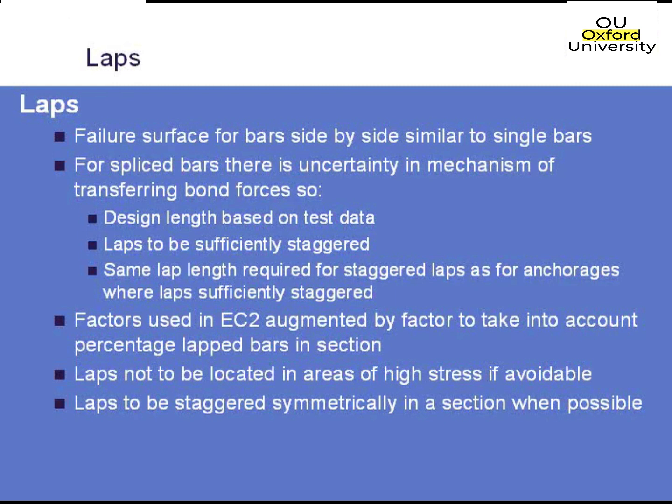Generally speaking, some guidance that you should be using is to make sure that you don't locate laps within areas of high stress if you can avoid it. You should also make sure that you stagger laps. Sometimes it isn't possible to stagger laps very well, particularly if you're coming in from a pile into a footing connection or something like that. In those situations, it is quite difficult to get your laps staggered. But generally speaking, if it's possible to stagger laps, you should stagger them.